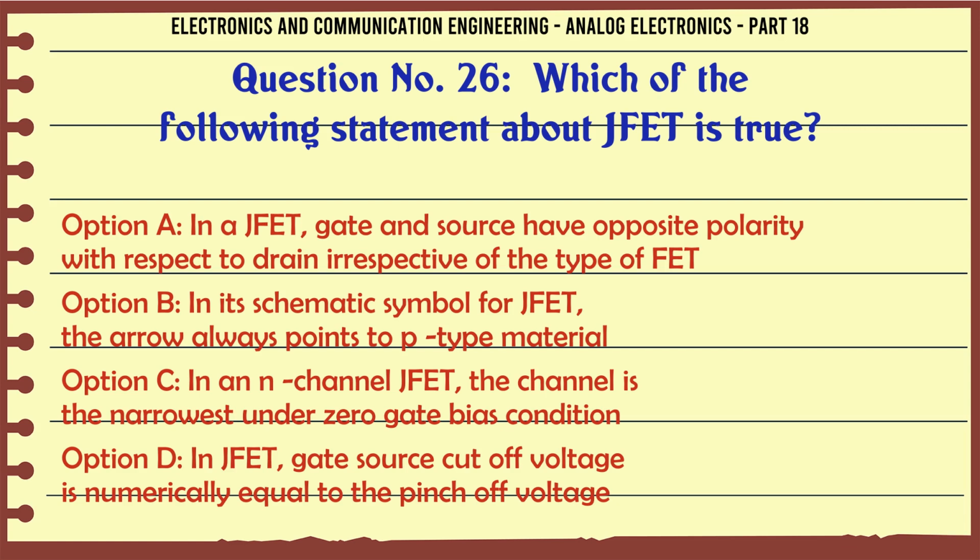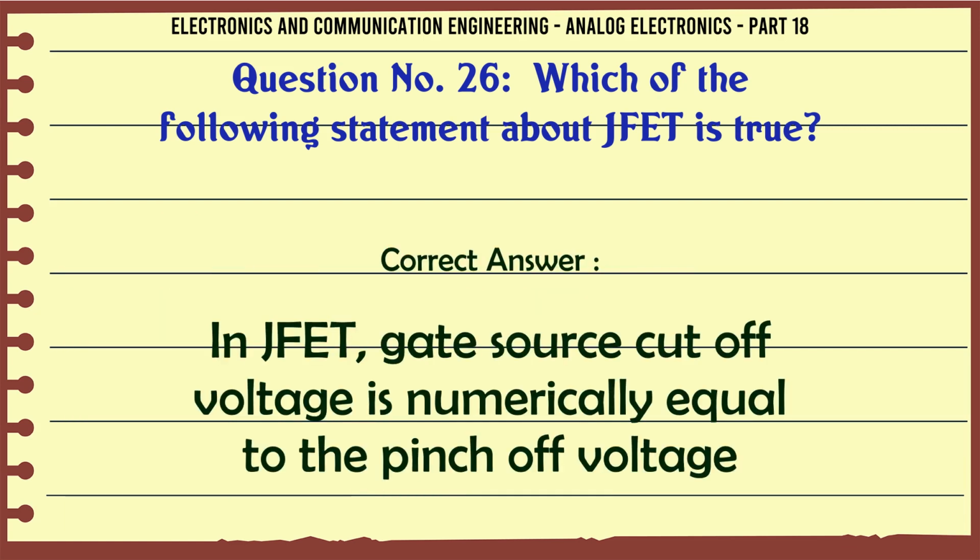In an N-channel JFET the channel is the narrowest under zero gate bias condition. D. In JFET gate source cut-off voltage is numerically equal to the pinch-off voltage. The correct answer is in JFET gate source cut-off voltage is numerically equal to the pinch-off voltage.